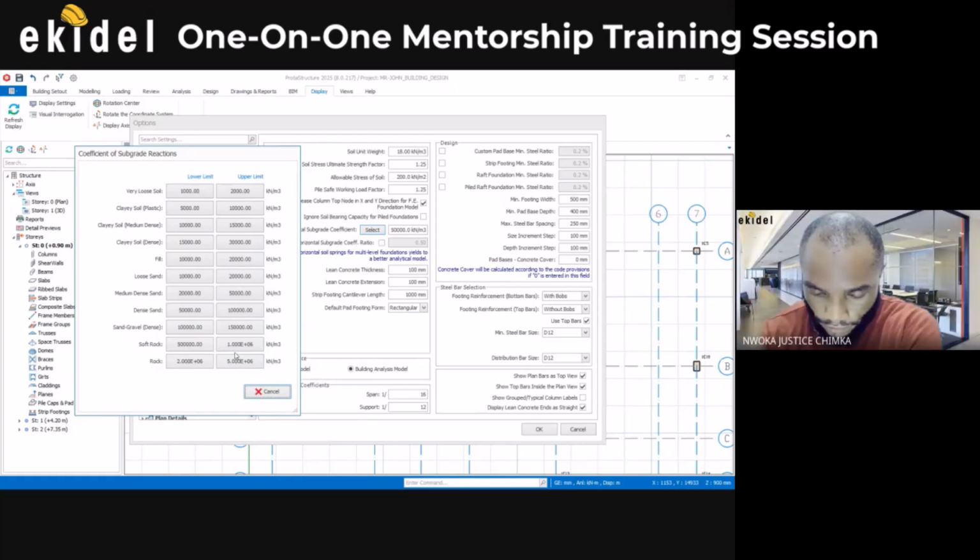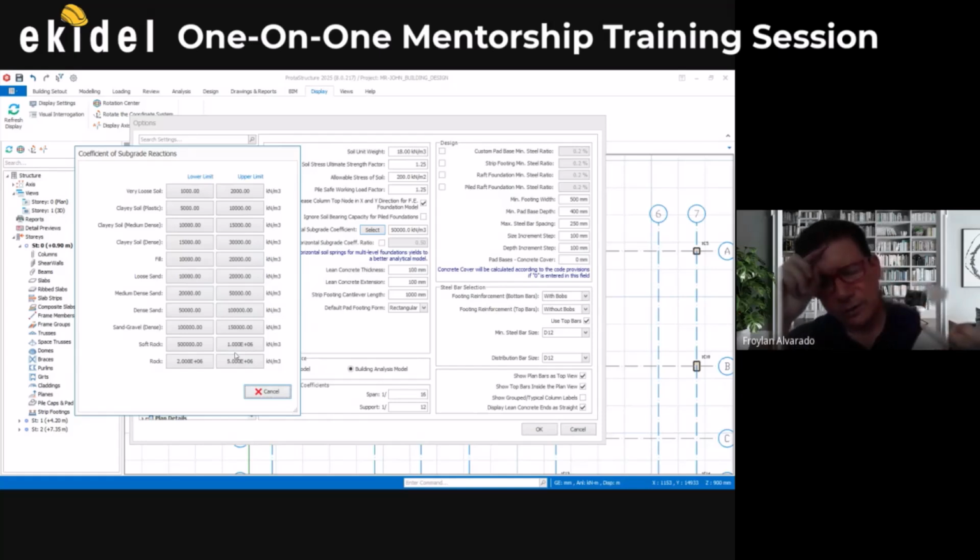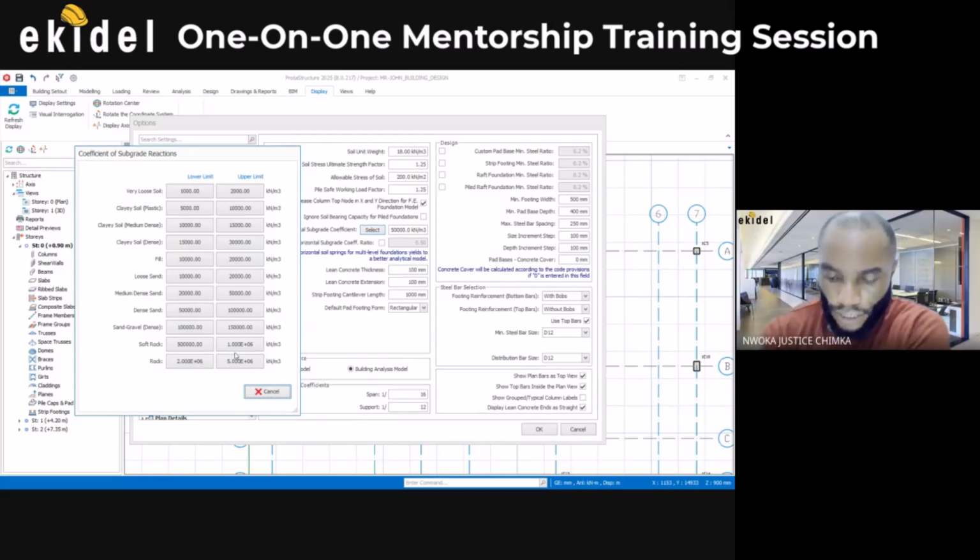So what happens is that we do pile caps over these piles, and that's how we would transfer the load down to the ground, to the limestone. So the limestone has a capacity of, I need to check it. But also, I think from the soil reports here, they went to a depth of 4.8 meters.